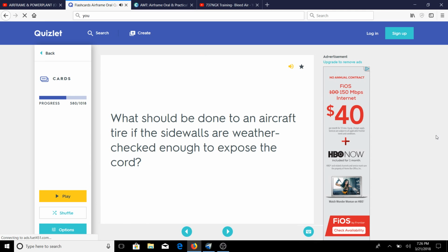How does a takeoff configuration warning differ from a landing gear warning? Takeoff warnings are usually intermittent horns while landing gear warnings are steady. What is the function of a Mach airspeed warning system? To alert the pilot that the never exceed airspeed limit has been reached or exceeded. What systems are commonly used to activate the landing gear warning systems? The throttles and the wing flaps.